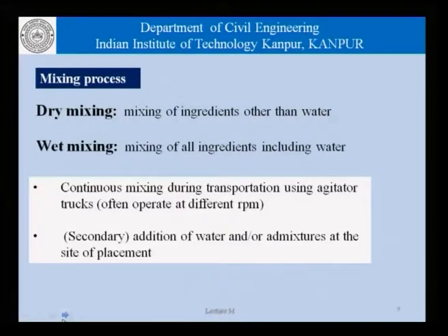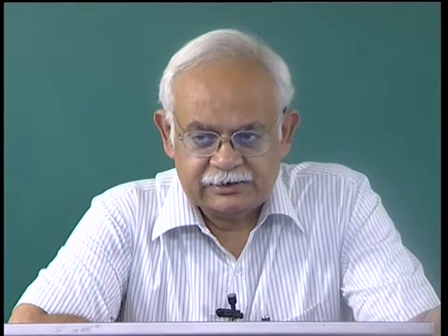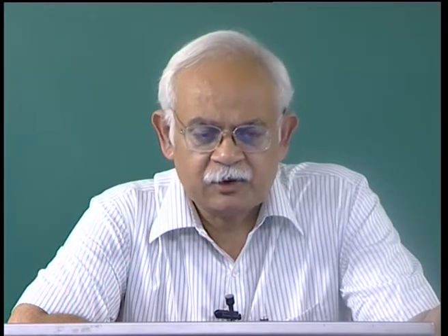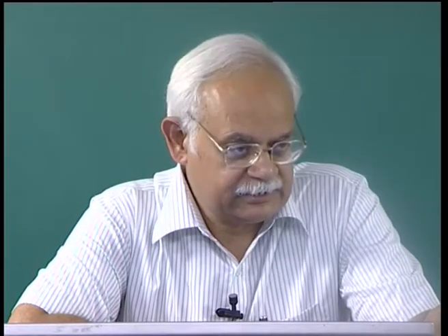Related to this issue is one of secondary addition of water and/or admixtures at the site of placement. Usually, all the ingredients need to be mixed at the plant and the concrete is transported in a manner that it is simply ready to place. In certain cases, however, it might be required that some water or some admixture is added to the concrete just before it is placed.